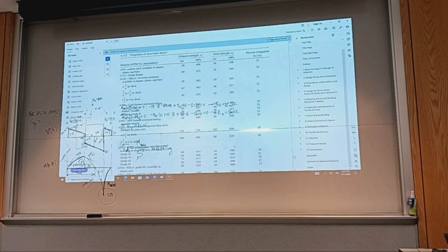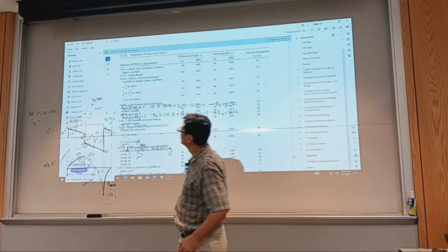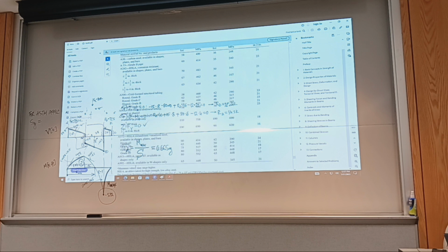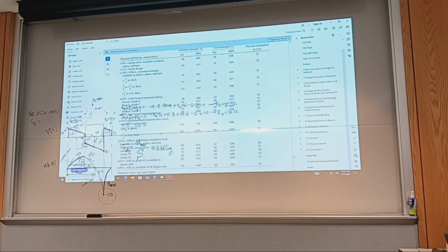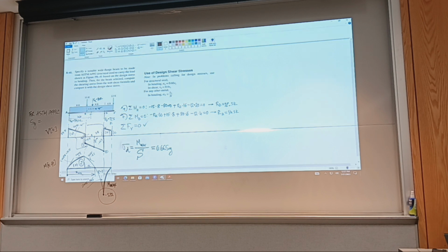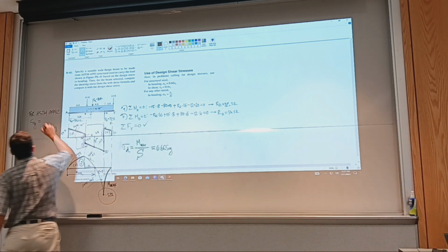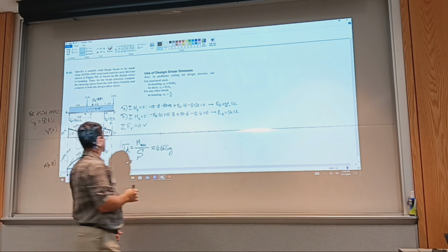and find where it says structural steels. Okay, so ours is, I wrote it here, 992. So 992, it's the last on the list. And we're interested in yield strength. So yield strength is 50 KSI. 50 KSI, okay? This assumes static loading. So 50 KSI right here. You saw from where we got it.